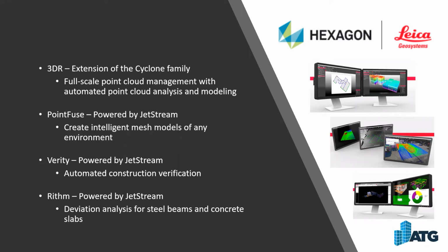And you can view heat maps right on top of your architectural drawings, and it has a full in-field workflow as well. So you can upload your drawings out in the field, and with the combination of RTC, you can do live updates there. Say you're doing a concrete pour, for example, and need to check the flatness before it fully cures. Rhythm would be one of the tools that could go into that.